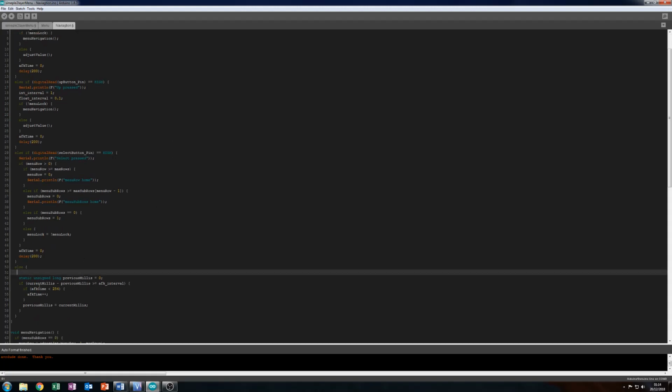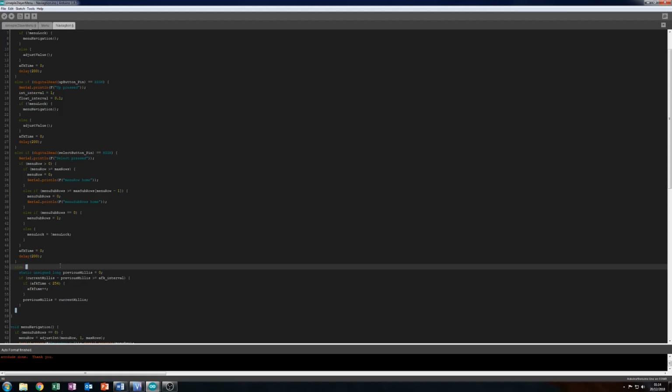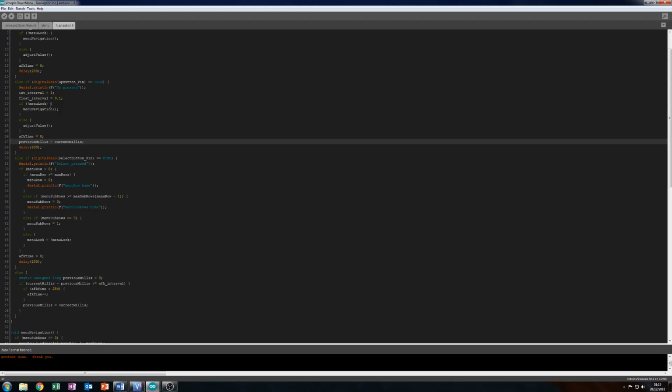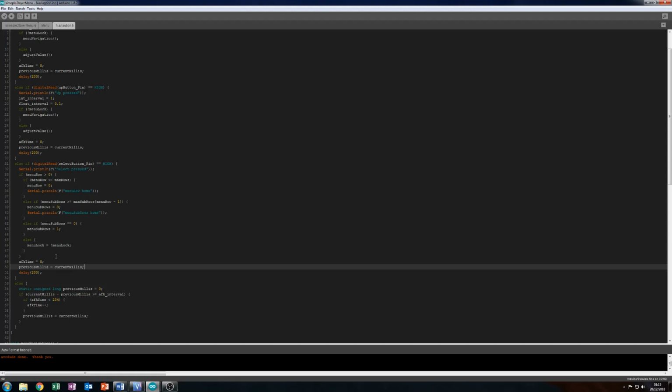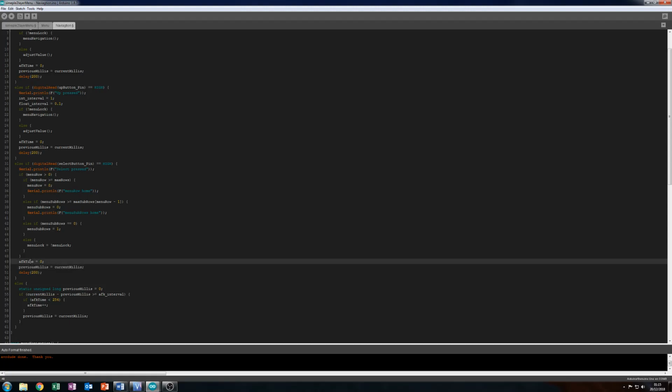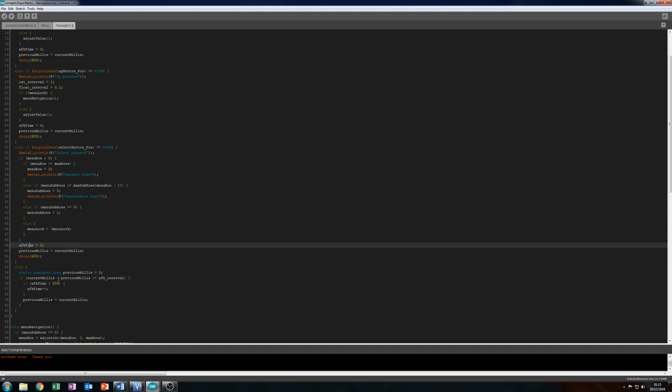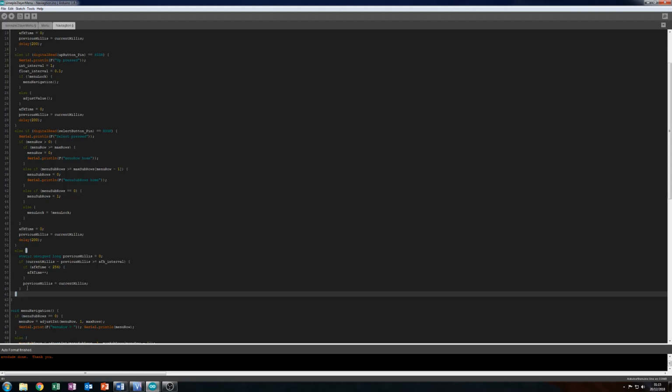And what we'd say is, if you press any of the buttons, not only will we set that to that, we'll set this to this. Because thinking about it, for the clever ones of you out there, setting that to 0 wouldn't be sufficient because the timer may set to 0, but then this may set it to 1 a millisecond later. So we really want to reset the timer as well as the counter. So we'll reset the timer and the counter if you press any button.